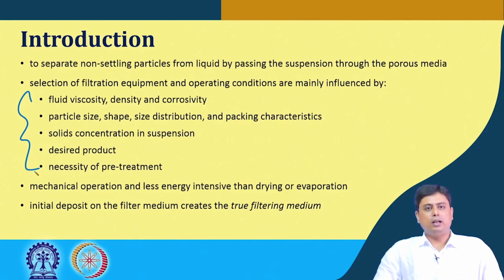The other important thing is the particle size, shape and the packing characteristics as well as its distribution. If we have prior knowledge of this size distribution, that helps us to propose the appropriate filtration equipment for that kind of suspension, because the size, shape, size distribution and the packing characteristics eventually dictate what the cake characteristics will be.